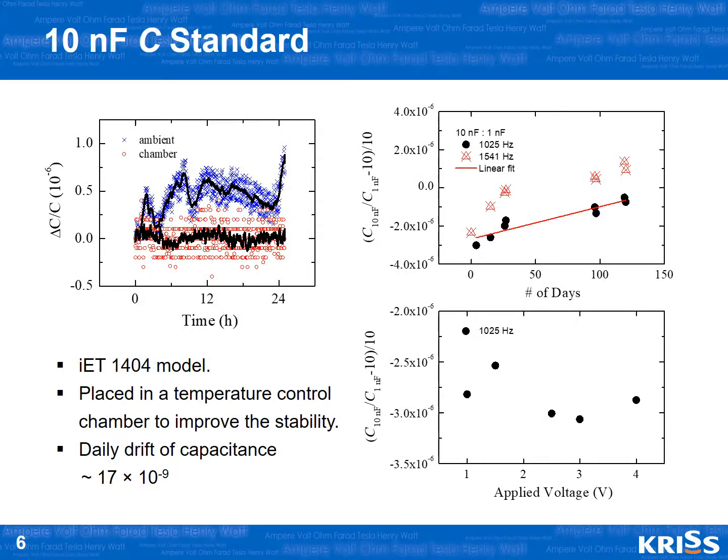The 10 nanofarad standard capacitance. The 10 nanofarad is a commercial capacitor, model IET 1404 10 nanofarad. The capacitance value is observed to have some changes under the ambient environment due to the large temperature coefficient of the capacitance. Therefore, it is placed in a temperature-controlled chamber, and the short-term stability has been improved, as you can see in the left figure.